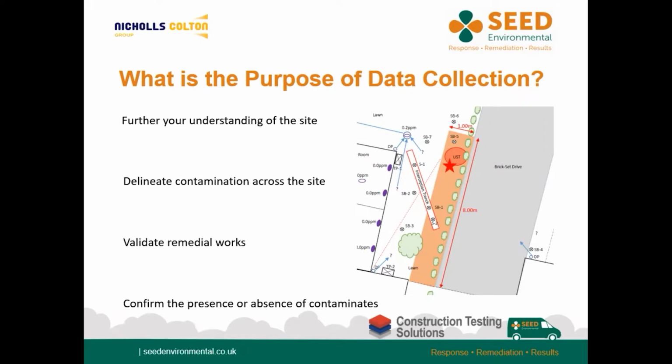Alternatively, soil samples can also be collected to validate a site once remedial works have been completed. This can be from open excavations following source removal, or possibly from a groundwater smear zone following the completion of in situ remedial works. The site plan included in this slide shows the distribution of a series of soil bores and trial pits around an overfilled domestic underground tank, which displaced fuel at the ground surface via its vent. The sample locations were selected around the spill origin to confirm the extent of contaminant migration into shallow soils and to quantify the risks known to receptors, namely buildings and the health of site users.